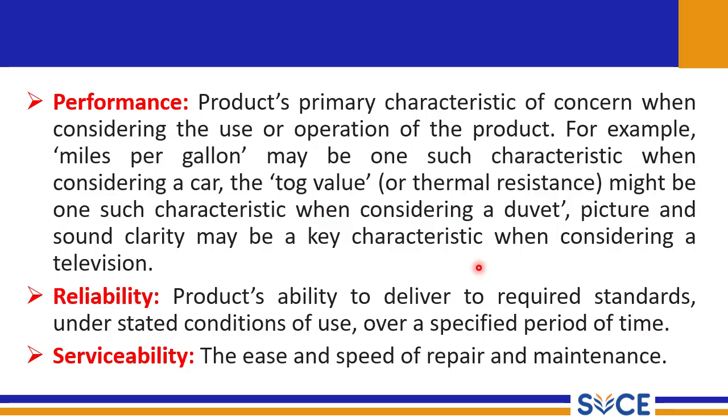Whether it's reliable or not, under basic standard conditions. Serviceability is another aspect. Serviceability means the ease and speed of repair and maintenance. How quickly you are able to repair it, how quickly you are able to maintain it and complete the maintenance process. That is called the serviceability aspect of quality.